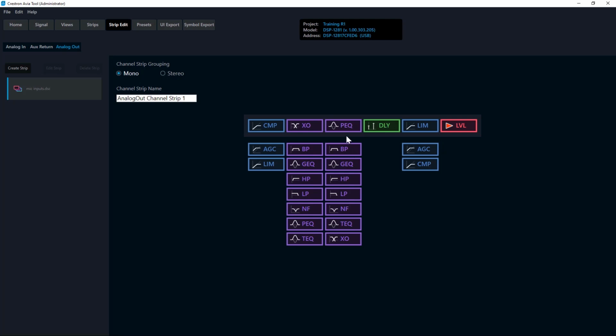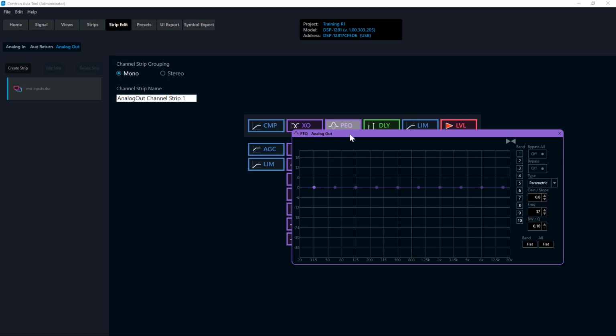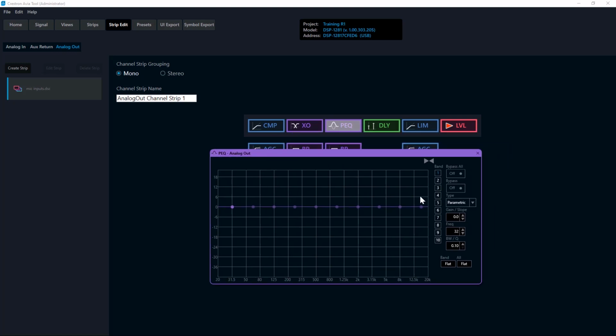Then, moving over to the PEQ, I see I have 10 additional bands of parametric EQ for tuning the room. Since I have 5 bands in the crossover, I may opt to change this one to a notch filter to deal with feedback. The notch filter has tighter Q controls per band, down to 0.05, so I can make very detailed cuts without drastic consequences to neighboring frequencies.